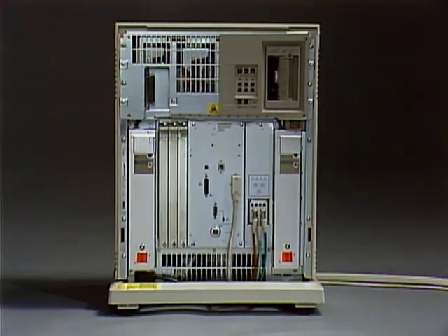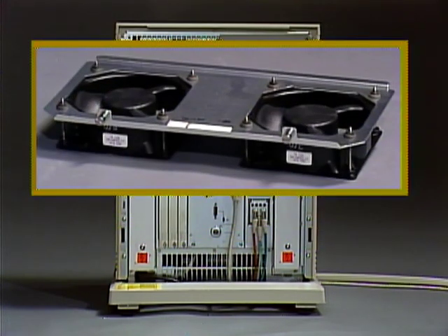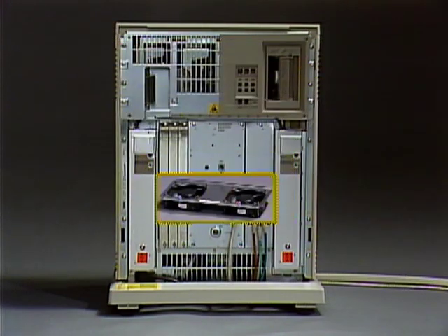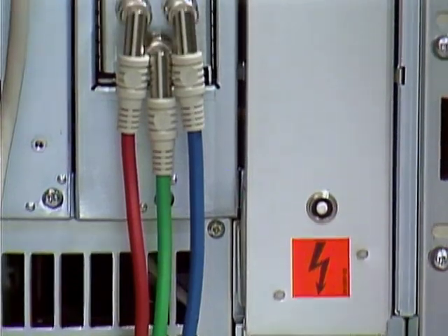Each power supply has a fan output that can drive two 4.5-inch DC brushless fans. In a BA213 system box, the right power supply drives both fans and the left power supply fan output is not connected. Each power supply has a resettable circuit breaker for overload protection.